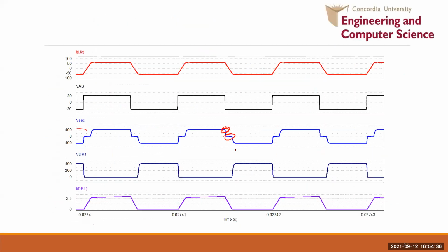Okay. So which is still there. Whenever the diode is changing, whenever the transformer is changing the direction, it is still there. But you can see after the snubber, the 800 volt has been clamped at 400 volt, so that the switching requirement can go down. But you can see this solution is a lossy solution.